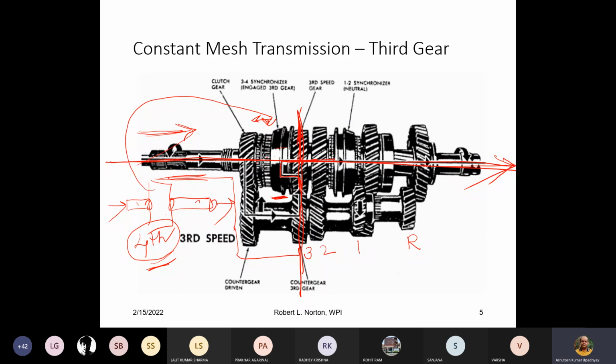So the fifth and sixth gear, what will they be doing? They will be creating an additional, higher speed ratio than the engine. So if the input RPM is 1000, the fifth and sixth gears are capable of creating a higher RPM, and the fourth one will generally be the straight line, I mean the input RPM equal to the output RPM.